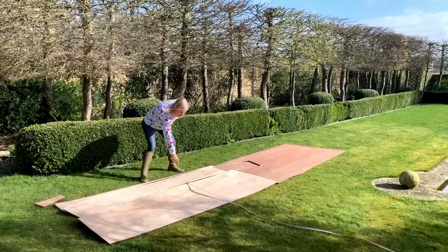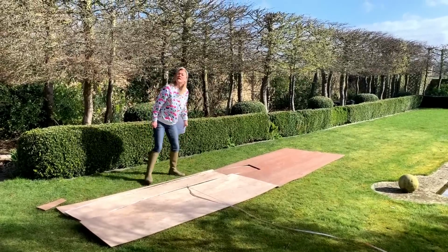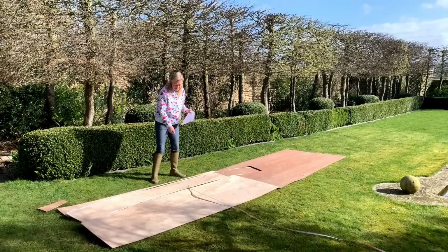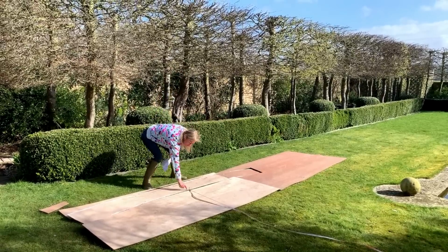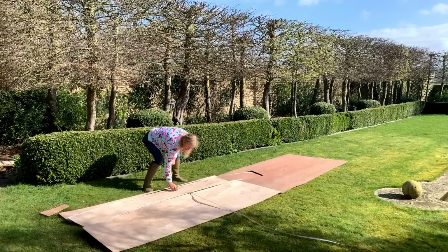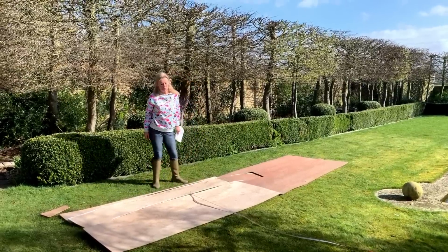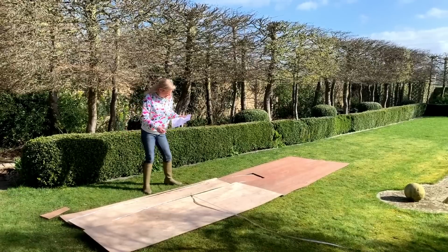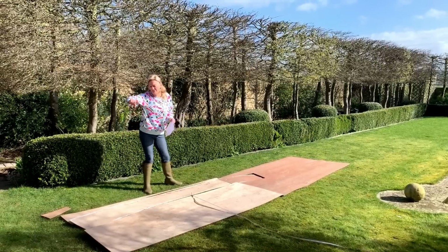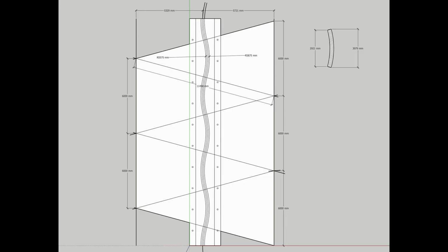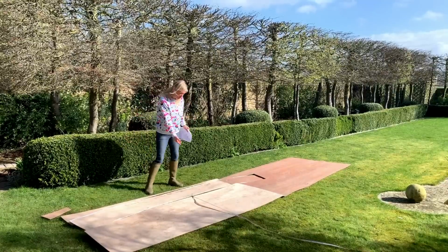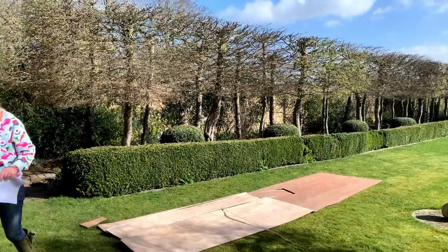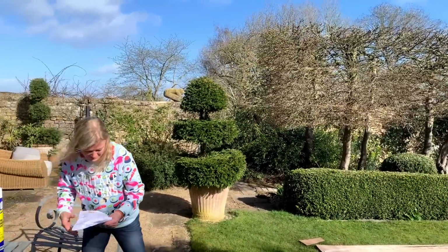And then the second radius is going to be 320 millimeters from the first radius. So it's actually 5.875 meters, this second radius. That's because I've got 3 100 sets with a 10 millimeter joint between them, which adds up to 320. Having done that and got the pieces at the end exactly the right angle, where the two curves on the serpentine meet, as you can see they're angled, then it's cut out, and there I've got my template for the serpentine.